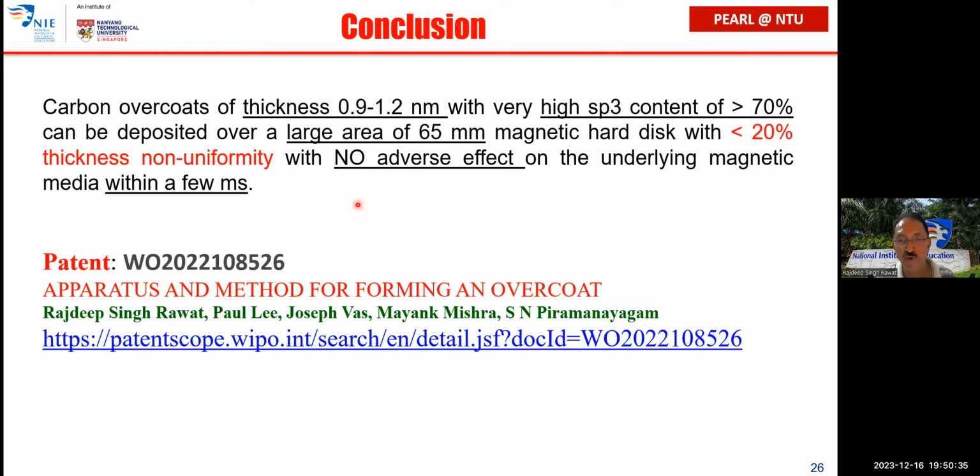In industry, at Showa Denko, in their deposition process for each disc, the carbon coating part has a 6-second window reserved for high volume production. We were able to do that. Imagine if you develop this plasma focus device with even 1 Hertz repetition rate, we are done. We are good. Because you have 6 seconds, we can do it within 1 second. In fact, we can do even faster than that, but they don't really need that because there is a certain feedback rate coming from there. So yeah, this is where I stop.